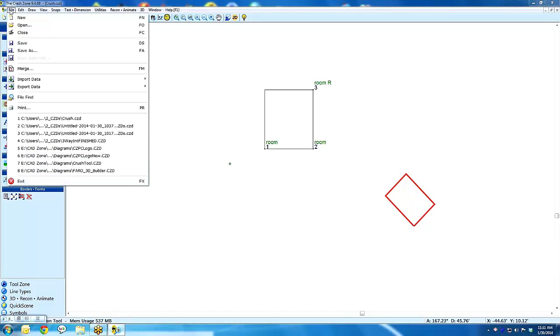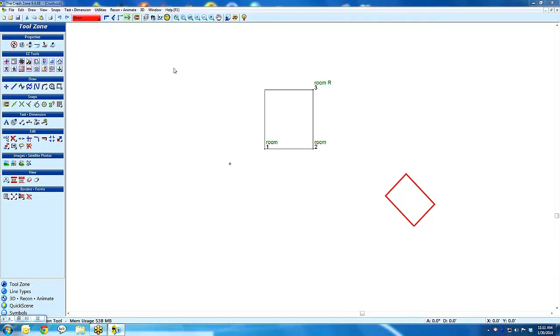We can allow you to actually do a file and merge, which means you can bring in multiple drawings and data, and then you could say, oh, I need to align this corner to that corner. So I would just do the same thing I did with that satellite image, just select it, go to the Align tool, and say, well, I'm aligning this corner, referencing it here to this point and referencing it there. And so you could have all your total station data in, combined with point cloud data, combined with hand measurements. No reason you can't mix everything up.